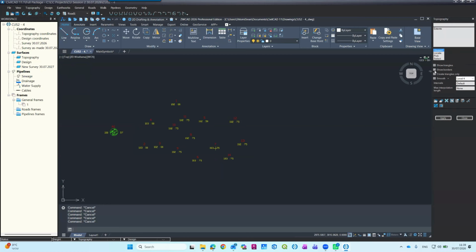For now, I see that the predefined is to show borders, to show the borders of my surface. There's no smoothness. Intervals are not predefined, so it defaults, so the system will select by itself. And later on, we'll understand the rest. So I don't want predefined. I want to use my own. I will use 0.25. And I press apply, and the system creates the surface.